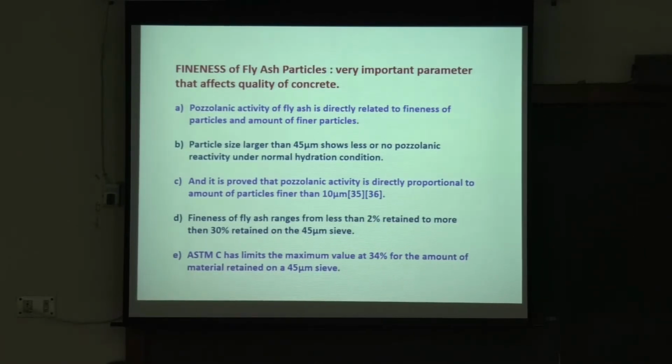If you use just a normal optical microscope, you can do that, but the advantage of the scanning electron microscope is that the depth of field is much better, much superior. For the same magnification, if you go for 200 times in the optical microscope, you can only see the very top flat. So the depth of field is not very good.